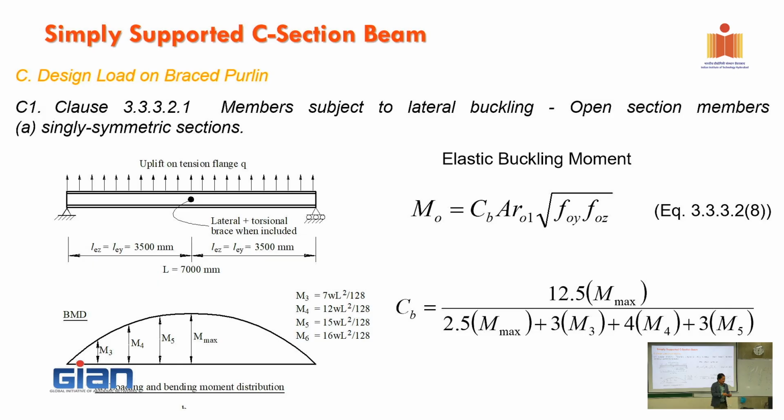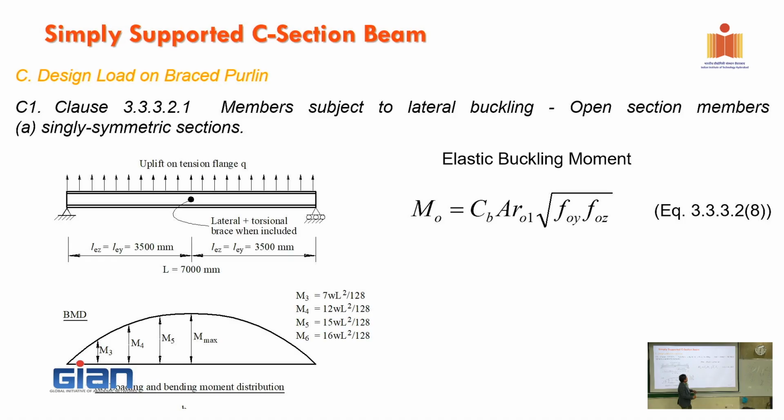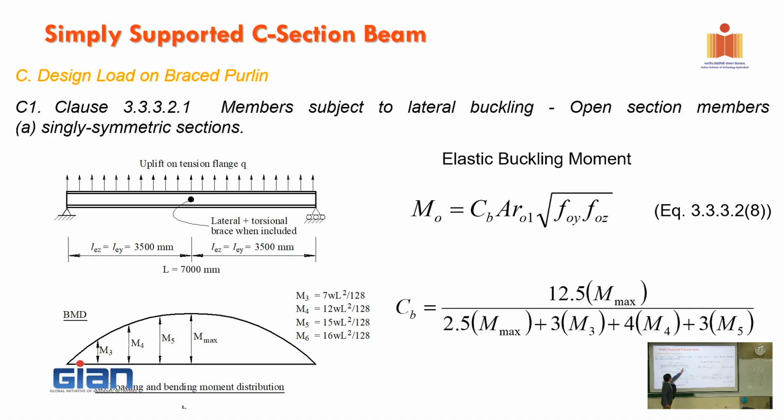Now in the case, if you design and you don't worry about the material, the boss says don't worry, so instead of putting one in here, you put 5 of them, lateral restraints in the beam. So what's going on? If you put 5 of them in here, the length in here will be reduced a lot.